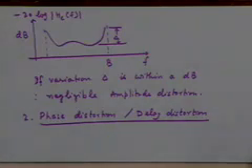And as the name implies, this kind of distortion arises when your channel has phase transfer function which differs from the required ideal transfer function. What is the required ideal phase transfer function? A linear function of frequency passing through the origin, right. Odd function, it has to be, of course any real filter will have the phase function as an odd function, that is not an issue. So if it differs from that linear characteristics within the bandwidth of interest, we get the phase distortion.